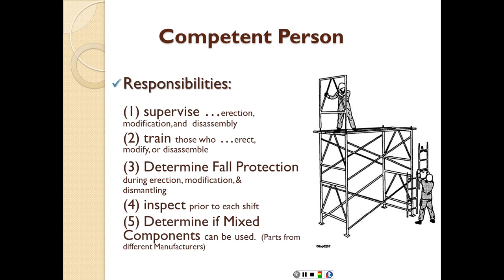The responsibilities of the competent person include supervision of the erection, modification, or disassembly of the scaffold; training those who are going to erect, modify, or disassemble the scaffold; and determining what kind of fall protection measures should be taken during erection, modification, and dismantling. Inspecting the platform or the scaffold prior to each shift, because again, if there has been heavy rain, for example, which has made the soil softer, now it can destabilize that scaffold. Or if you have placed too much material, bricks or blocks or whatever, that may make it weaker